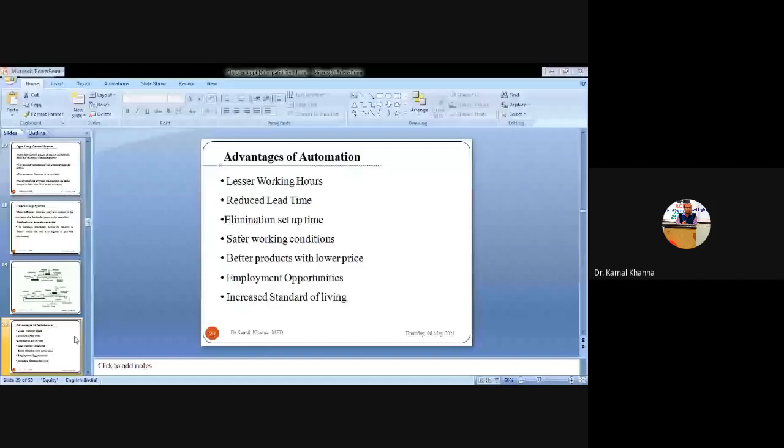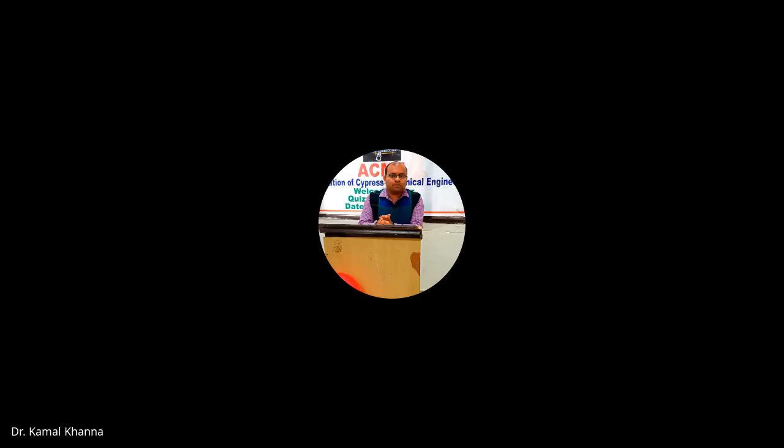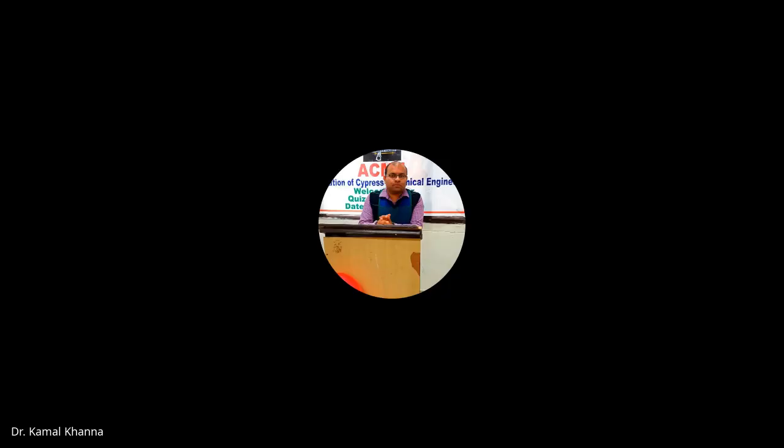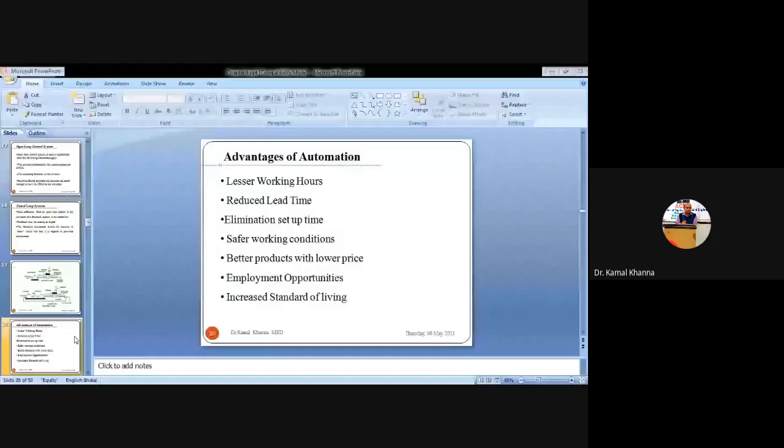We have eliminated the setup time, that is, the loading and unloading time we have reduced, because in earlier times the skilled workers were assembling the specimen, uninstalling the specimen, and fitting a tool at the desired angle. But here, with the help of a set of instructions, the machine fetches the instructions from the control unit and performs the operations by fetching the tool from the tool library onto the specimen, and there will be no setup time. So we have reduced the setup time.